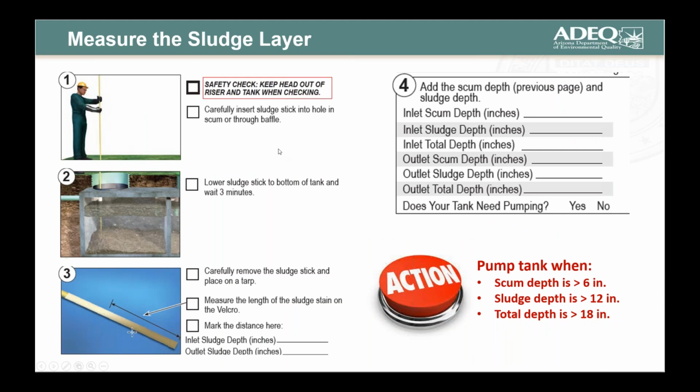Okay, next you're going to need to measure the sludge layer. So you're going to carefully insert the sludge stick into a hole in the scum or through your sanitary tee or baffle right here.